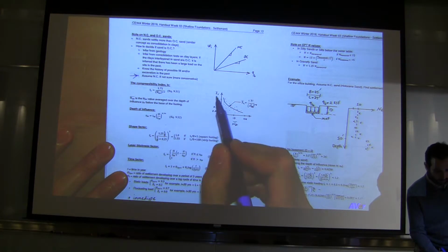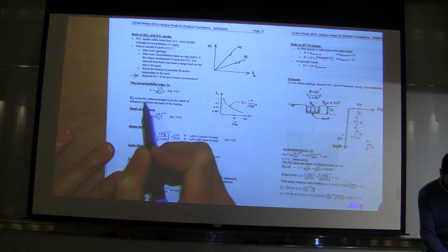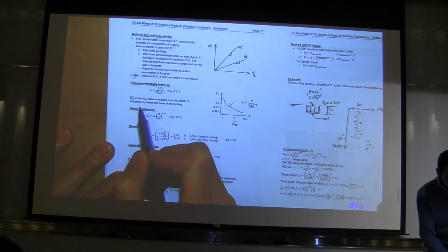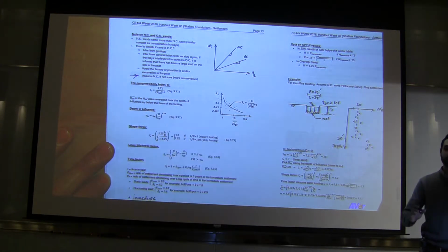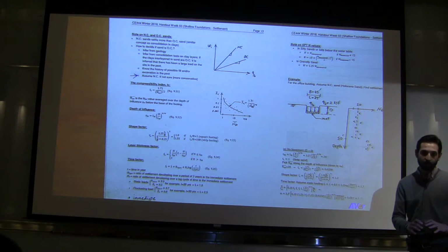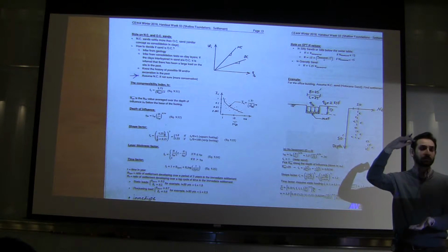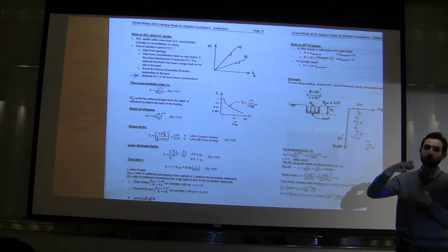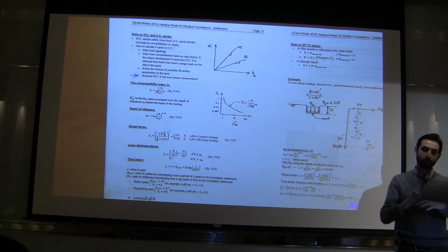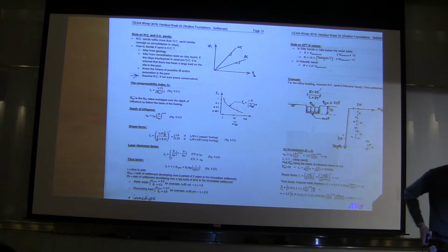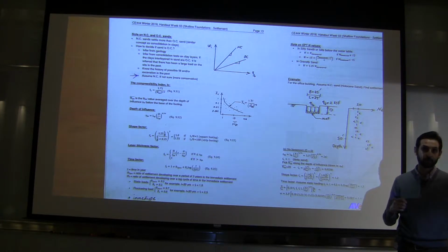So researchers looked at data of I sub C versus N60 bar, and N60 bar is the N60 values averaged over the depth of influence, or Z_I, below the base of the footing. I'll talk about what depth of influence is, but before getting confused by that, N60 bar is basically the average N60 below your foundation, over the depth that you think is more reasonable. So we'll talk about what depth is reasonable for that. But if you look at this equation, as N60 increases, I sub C decreases, right?